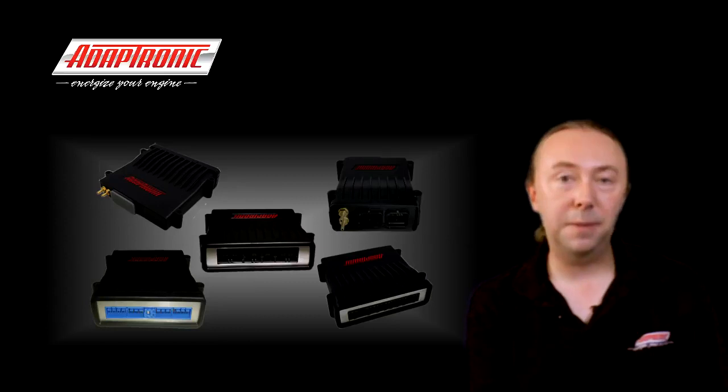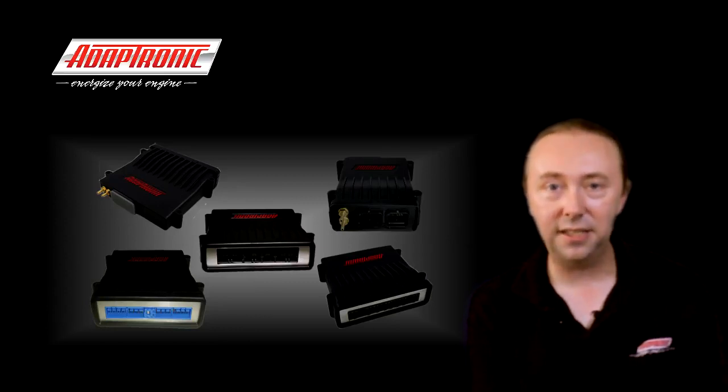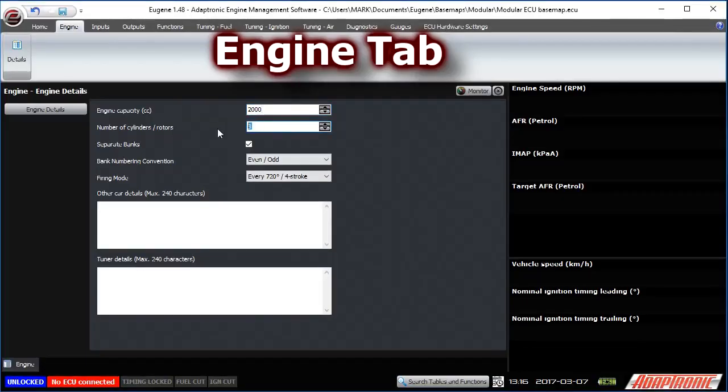Now this is the actual swept volume of the engine. You don't double it for a 2-stroke or rotary or anything like that. It's just the swept volume of the engine. Now the next setting is the number of combustion chambers, number of rotors or cylinders. So 6 for a JZ engine, 2 for a 13B, that sort of thing.